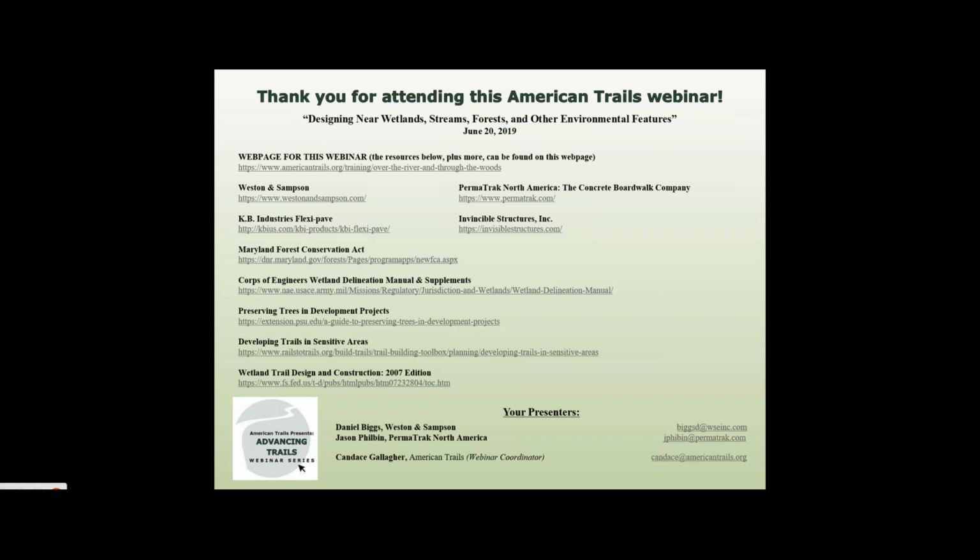Thank you. Brendan asks, for bridges with widths smaller than 7 feet, what are the vehicle weight ratings, and where does one find those limits? Are those national standards? I'm not aware of any national standard codes. No, the design code simply says that you have to look at a 90 pounds per square foot pedestrian loading. Vehicular loading would be specific to whatever the use is. Generally, I've heard that users just want to run a maintenance vehicle over the top. There are no design codes that define exactly what a maintenance vehicle is.